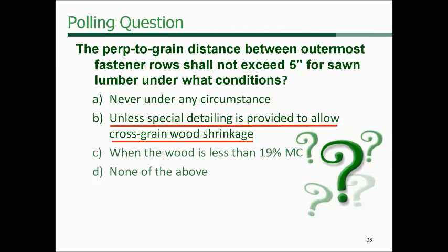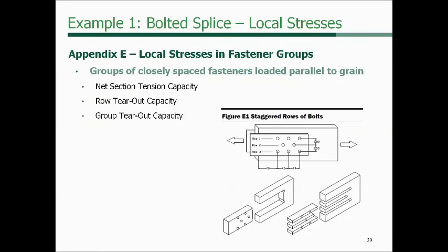Also, something new to the NDS is an allowance for glued laminated timber to have a larger than 5 inch distance between those as well. So take a look specifically if you're using glulam timbers. All right, Appendix E. So I said we weren't done.